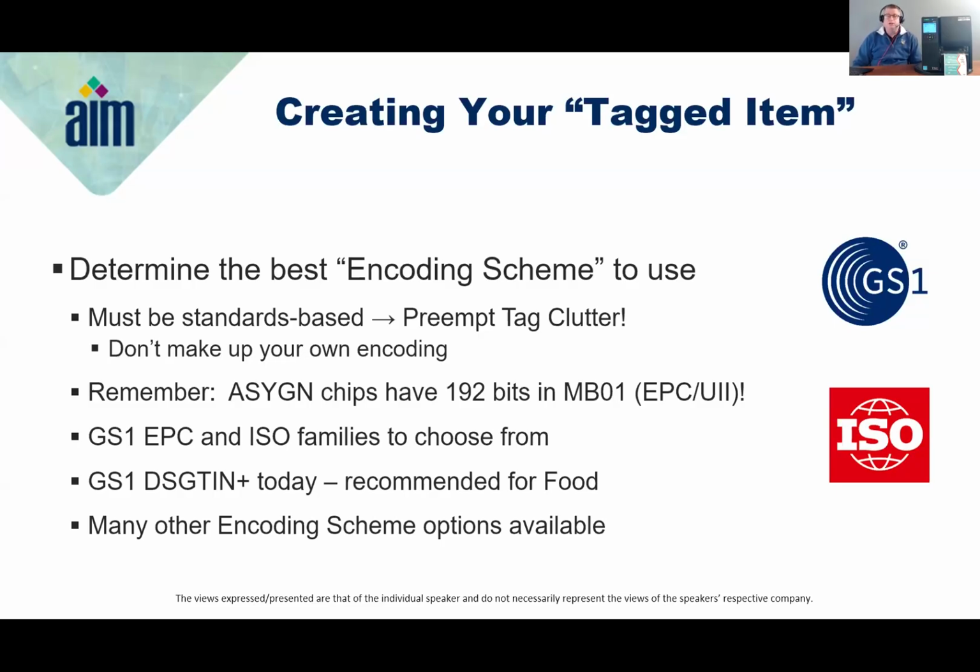The solution to this is to use a standards-based encoding scheme. By using a standards-based encoding scheme, you can uniquely identify your items, and you can set up your reading system to filter only for your tags and to ignore tags from other applications.